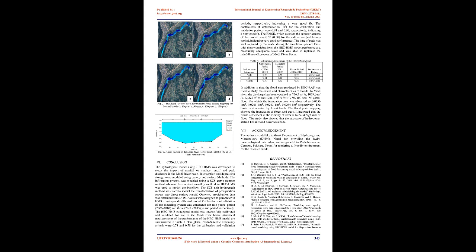The inundated area and maximum water level given by HEC-RAS during 10, 50, 100, and 150-year floods is tabulated in Table 9. The highest values of water depth during 10, 50, 100, and 150-year floods in this river are 8.36, 8.56, 8.67 and 8.71 respectively.